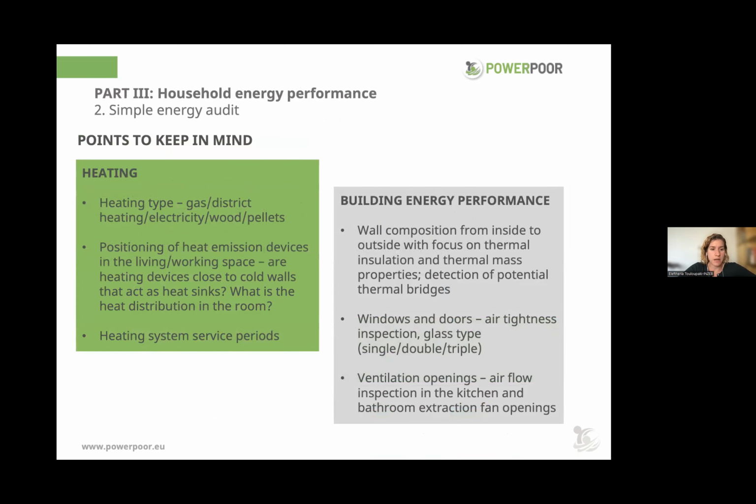Some points to keep in mind when considering the heating system: of course, we need to see what is the heating type, the heating fuel, where the emission devices are positioned in the living or working space. If there are heating devices that are close to cold walls that can act as heat sinks, and what is the heat distribution in the room, and what are the service periods of the heating system.